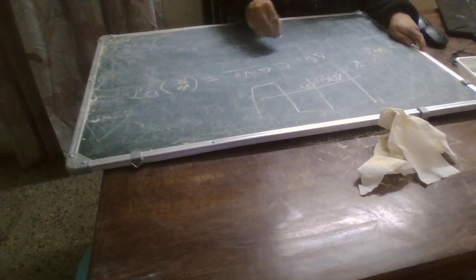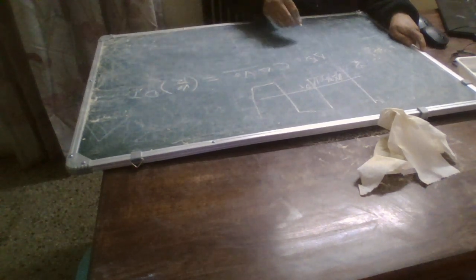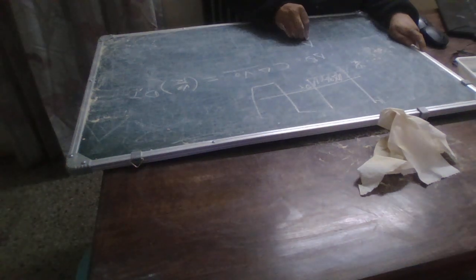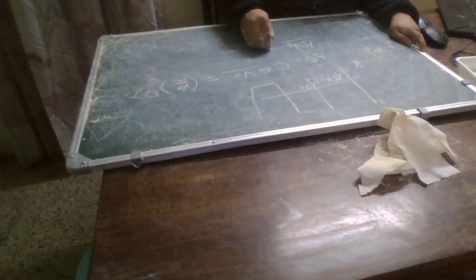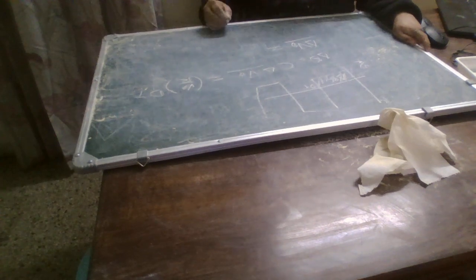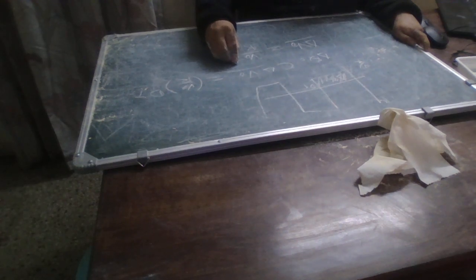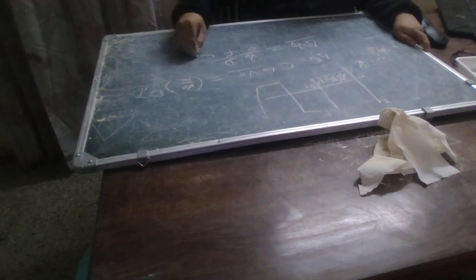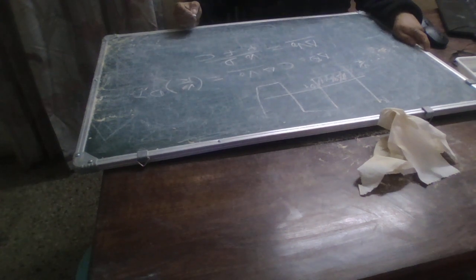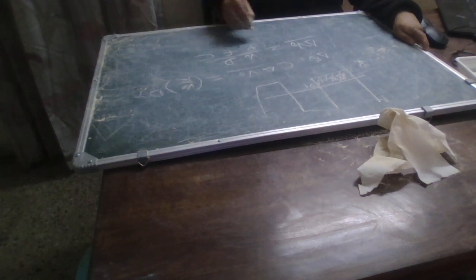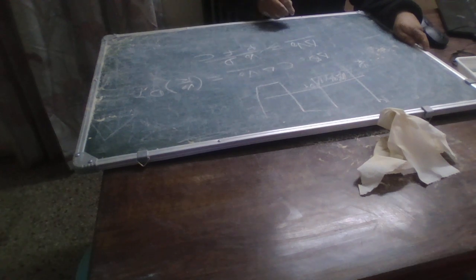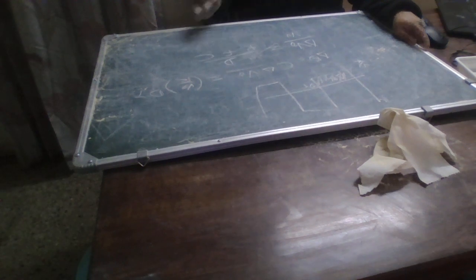Taking these two equations, we can very easily say that delta V naught, the peak to peak variation of the ripple voltage, is V naught by R. Then dt we can put as 1 by F, frequency, and we have C. If you have to take it as a fraction of the output voltage, we can take V naught here, and the expression would be this.